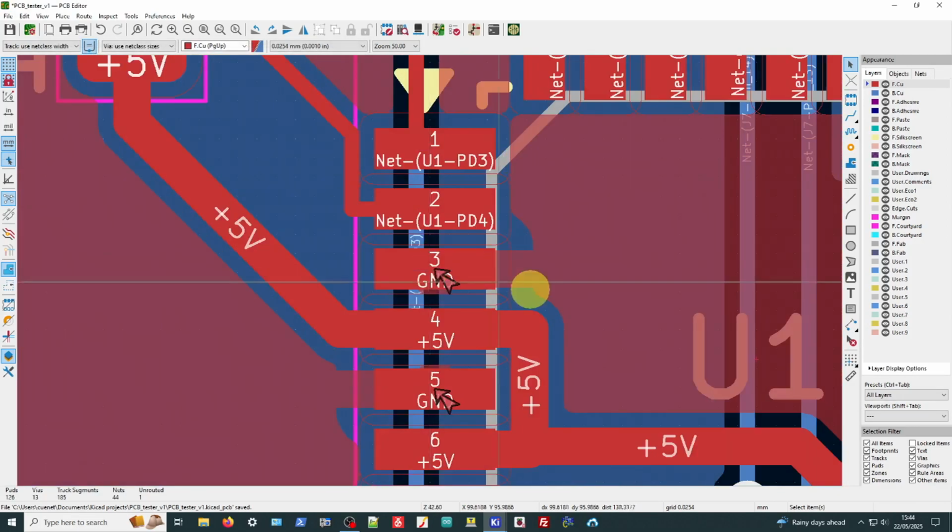What it's telling us is, this is obviously the MCU, it's expecting 2 spokes, or 2 connections if you like, to this ground pin, and we only have 1 at the moment. If we click the little arrow there, it tells you down here, thermal relief connections to zone incomplete. Spoke count should be 2, actual 1. So it's telling us that there should be 2 connections. What it means is that this should be ground here as well. We've got the right hand side one, but there should be one on the left.